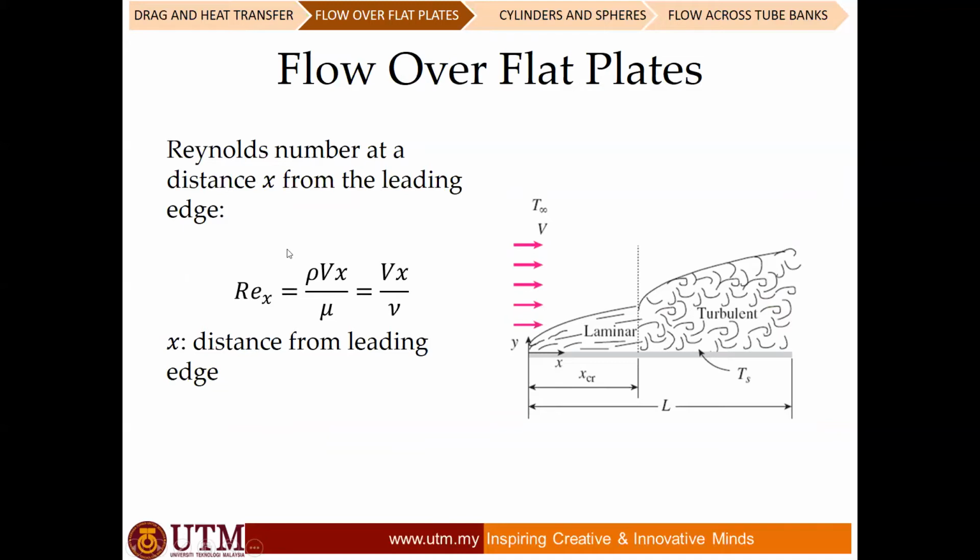Okay, so calculating the Nusselt number. Let's say you want to calculate the Nusselt number based on its length. You need to consider the value of speed at a certain point, which is why we have Vx and the Reynolds number at point x. Otherwise, if you are given the average velocity, you can calculate the average Reynolds number rather than the Reynolds number at a certain point.